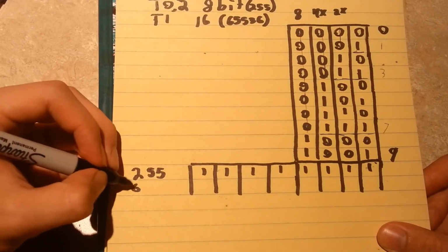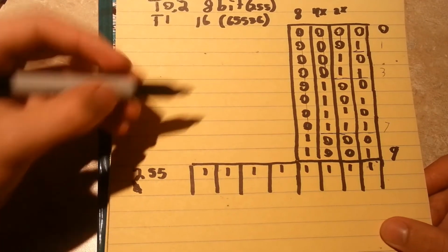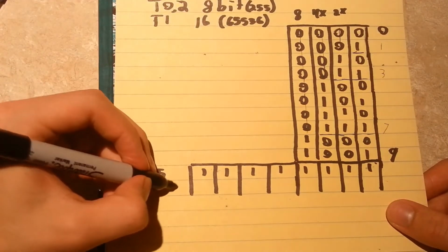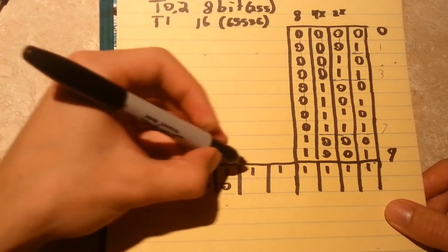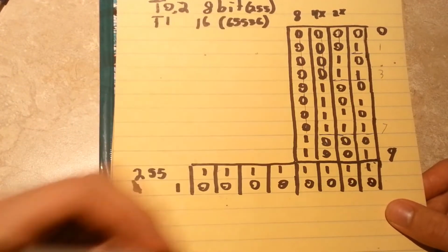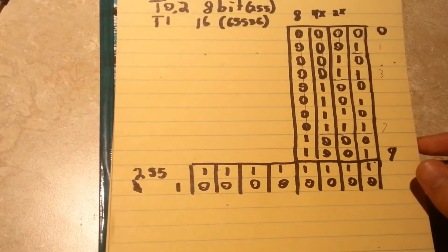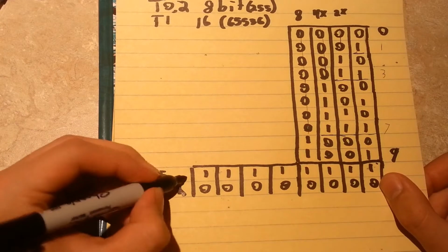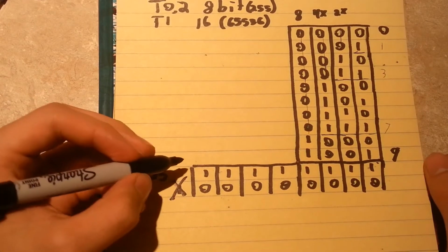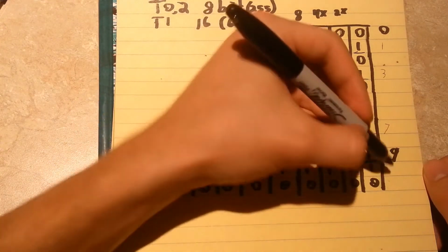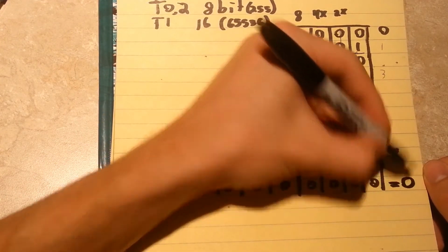256, following our carry pattern, would be 1 in the next column with zeros the whole way across. However, there's no more room for this carry bit, and so it gets ignored. And the result is the value currently stored in the counter is equal to decimal 0.